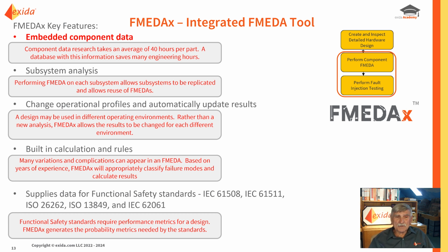FMEDAx also allows you to do subsystem analysis, where you can take an architecture block, enter all the components that are part of that block design, calculate all your metrics, and then save that entire subsystem for reuse later. Pretty cool if you want to reuse an old design. FMEDAx allows you to change operational profiles even after the FMEDA is done. Well, I've got an FMEDA for this environment. What are the failure rates if the temperature goes up? Change it, and the metrics recalculate automatically. Pretty cool.